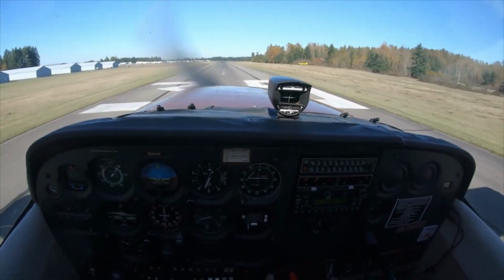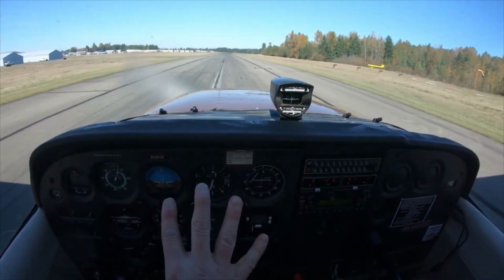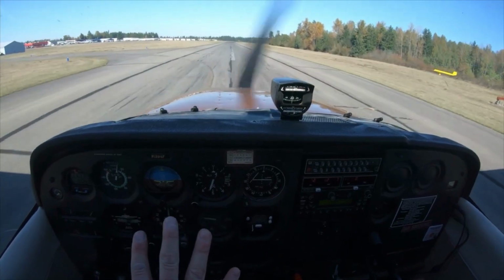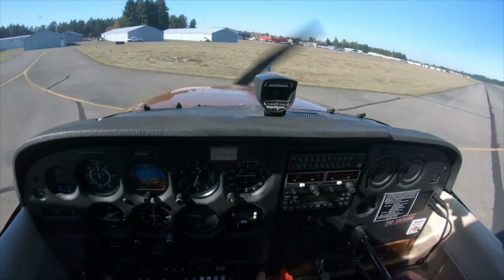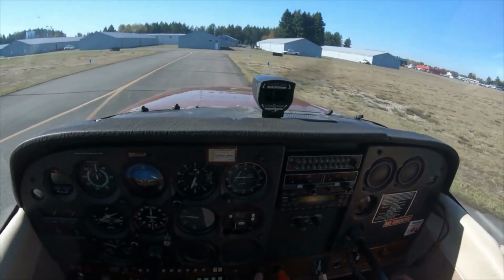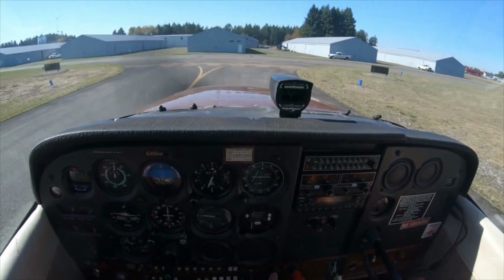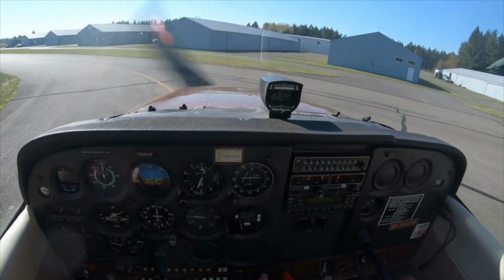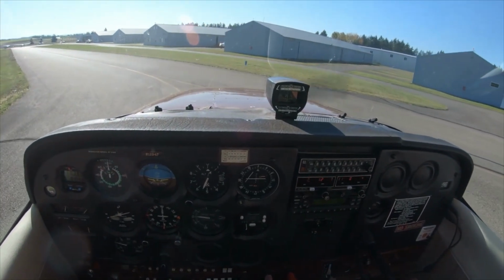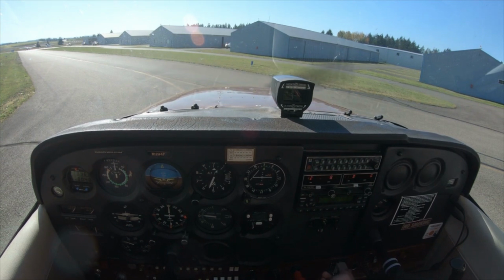Common errors. Common errors in the performance of short-field approaches and landings are: 1. A final approach that necessitates an overly steep approach and high sink rate. 2. Unstable approach. 3. Undue delay in initiating glide path corrections. 4. Too low an airspeed on final resulting in inability to flare properly and landing hard. 5. Too high an airspeed resulting in floating on round out. 6. Prematurely reducing power to idle on round out resulting in hard landing.